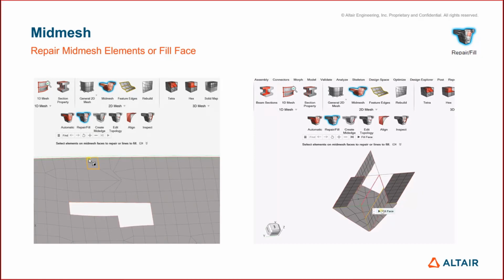In the case of repair, it's either a surface selection, a patch of surface that can be filled, as well as the loop detection. So if you click on a single edge, you would see here it highlights the complete loop that goes around. Wherever you have multiple loops, you can fill them quickly by selecting one edge and then clicking fill. It fills each face at a time. This is much more efficient than when we delete the not-so-corrected mid-mesh extracted output.